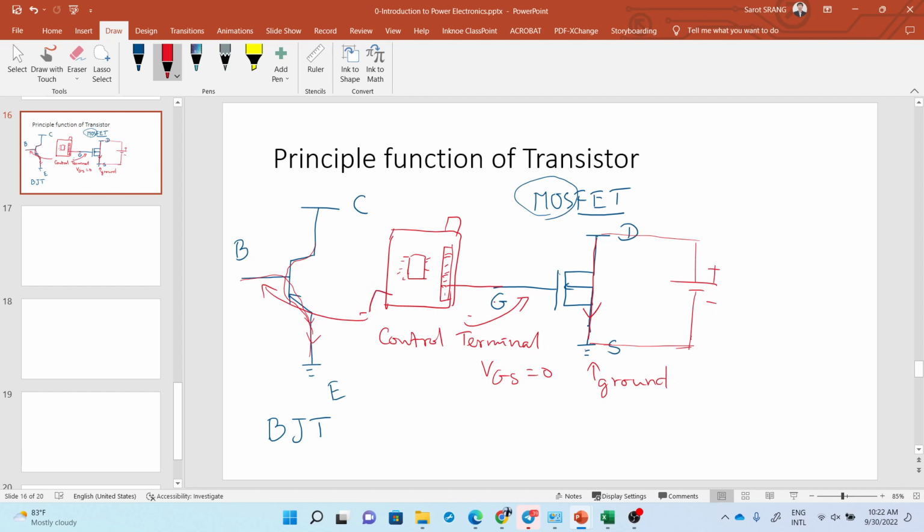Of course this one also has ground, right? So you program it to send a signal here to switch on, outputting a digital voltage like 5 volts, mostly 5 volts, and then you can turn this one on. So in some sense you can control it with a microcontroller. You program the task for the transistor to turn on or to turn off.